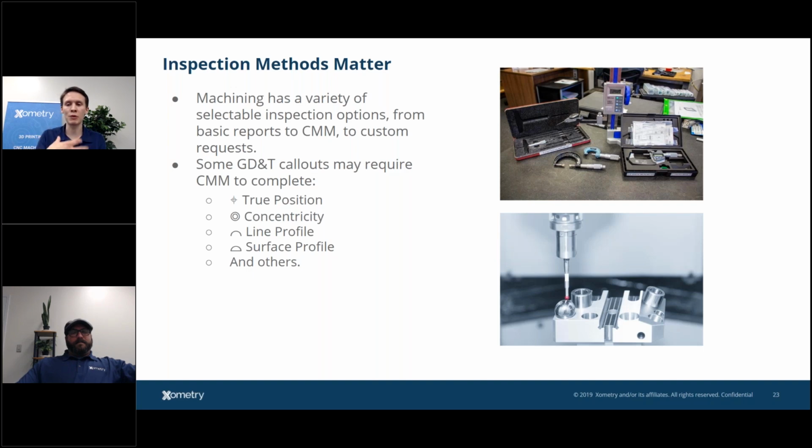So just understand that when you're looking at your part and your design, sometimes a certain feature, especially large spherical contours, or off-angle datums, say it's a manifold with multiple port features, that's probably CMM. So you don't select for the cheapest inspection if you know it requires CMM, because it'll probably require CMM if that's your feature set here.